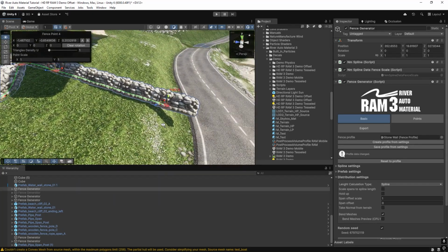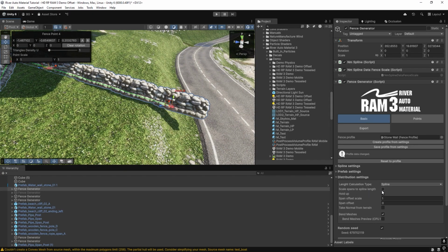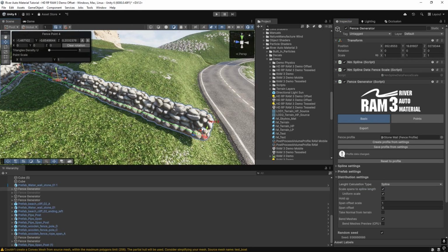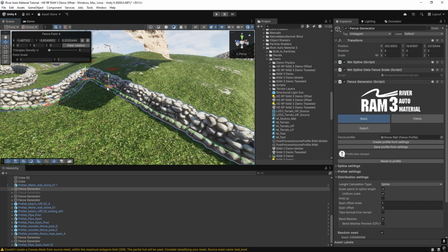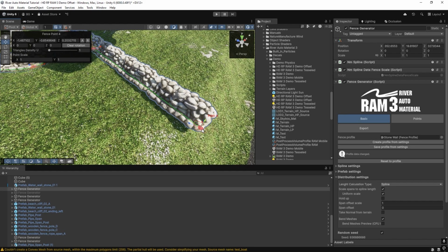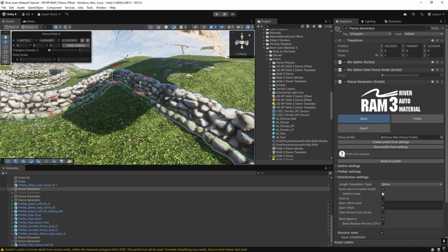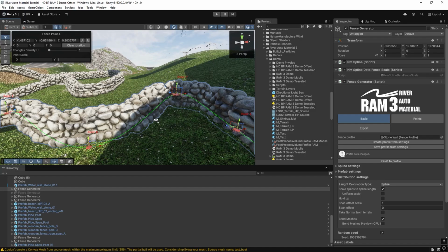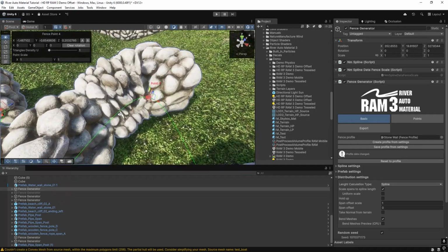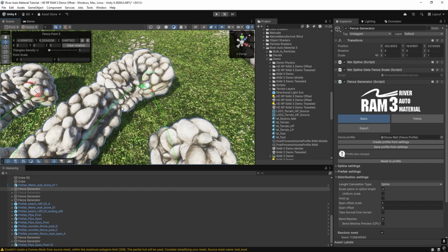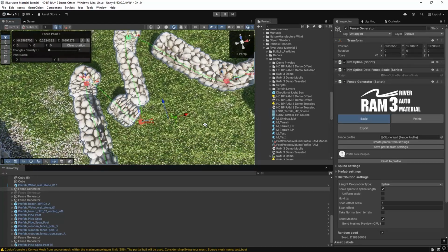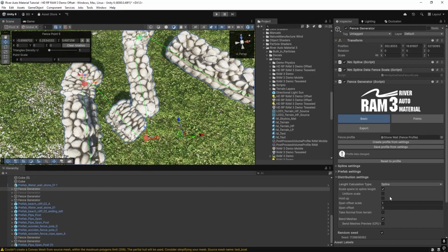So that's why you could use scale spans to spline length. This will force and rescale all objects between points, so they will always end at the spline point. You could use uniform or non-uniform scale. If you use non-uniform scale, you may notice that it sometimes could have a problem with distribution.